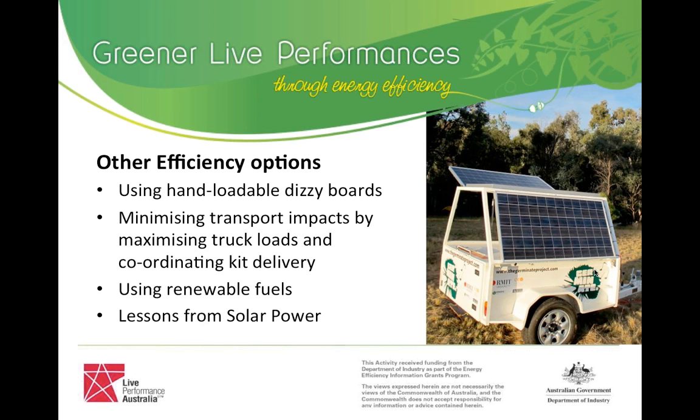Another point that I wanted to bring up was the corralling of generators into those loads that we've been speaking about before, the loads that need to run 24/7 and the loads that can be turned on and off. The other thing is we don't want to see too lightly loaded generators, because then the generators aren't working at their optimal best.